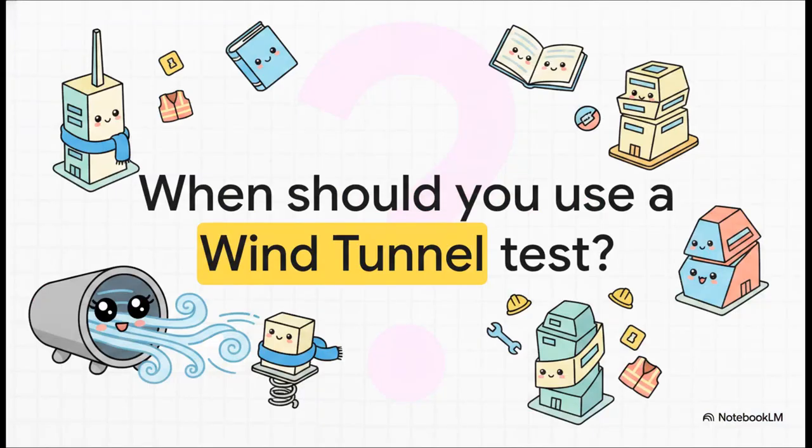So, I want to leave you with this provocative thought. At what point does your target reliability demand you step away from the formulas and put a physical model straight into the wind tunnel? The boundary layer wind tunnel remains the absolute workhorse for the most accurate information on design wind loads. When you are dealing with extreme aspect ratios, low structural damping, or highly complex architectural forms, the simplified procedures of the standard simply aren't enough. Ensuring safety means knowing when to close the book and when to test the real physics.